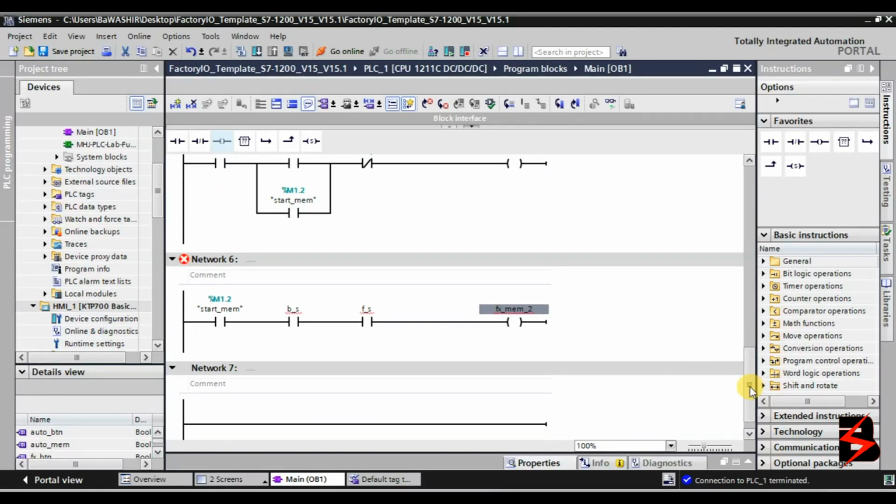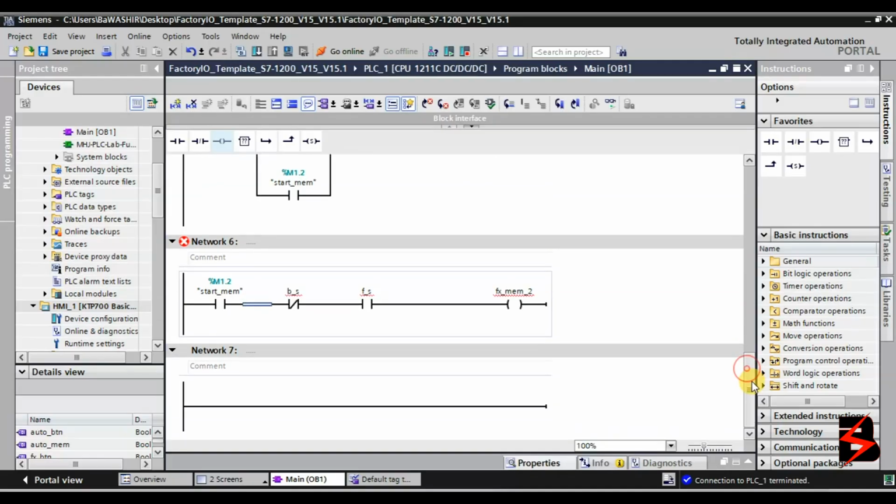So it is going to be, this one is normally closed. Now here, these sensors, it is because we are using normally closed sensors. This one would have been normally closed, but it's going to be open so that once a sensor signal comes, it closes it. This one has to be closed so that when the sensor signal comes, here sometimes it is confusing. I don't know how I can clarify it. So, if not that one, this one can still be initiated by the start button.